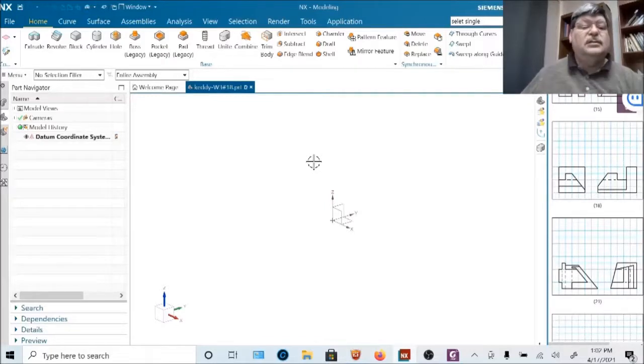Okay. Let's just start in here. You can either sketch or you can extrude. Now, sketch is the first part of extrude. What solid modeling is, the simplest form, is you draw a two-dimensional sketch and you extrude it. If you draw a one-dimensional sketch or a line and extrude it, you get what's called a ribbon, or just a two-dimensional surface. If you create points and do a closed geometric shape, like a circle, and extrude it, you'll get a solid when it extrudes.